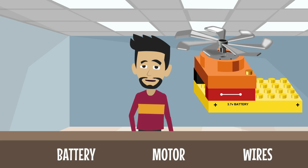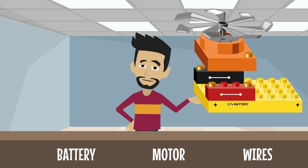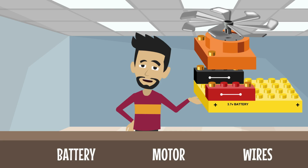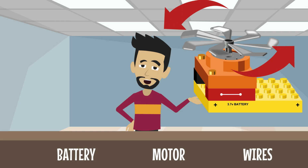To get the motor to spin the opposite direction, we need the current to flow the opposite direction. But the current can only flow one direction out of a battery. By turning the motor around, though, we can connect the other terminal to positive, which sends the current the other way. That will then make the motor spin counterclockwise.